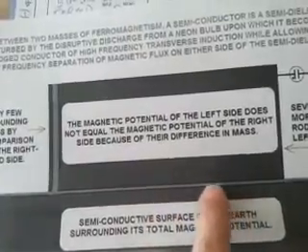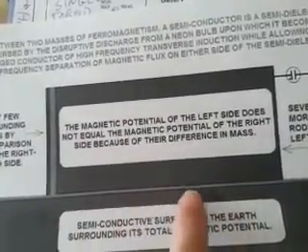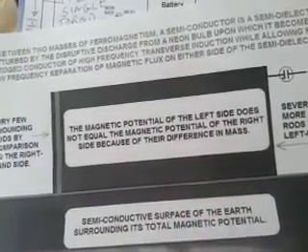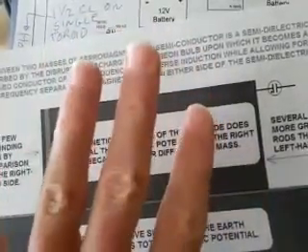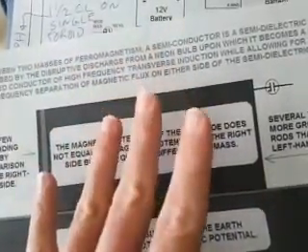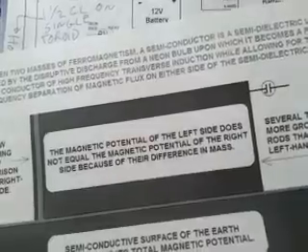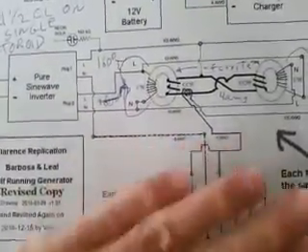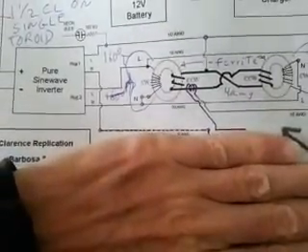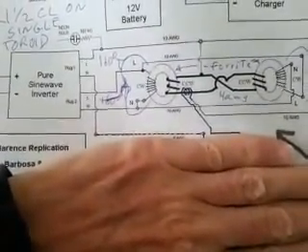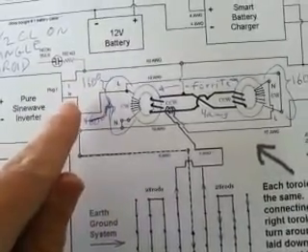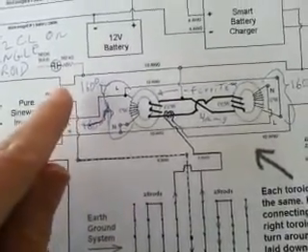Because this divider is also going to be shorted out. So it's as if the grounding rods won't even be there when it rains, let alone the difference in number between the two groups. It's like they're not even there. It'll be as if you just had no break at all, and you just had a wire go across here. And so that'll mean that the neutral will be the same voltage as the line.